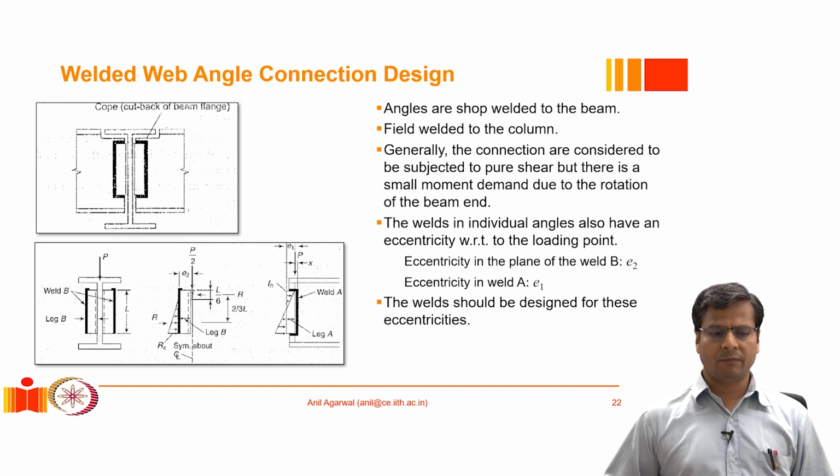But if we need to, then we know the process to follow, and to be on the conservative side, some designers prefer to do that. In fact, the textbook by Dr. Subramanian also recommends the same method to be utilized. Here you might also notice that in such situations we should always provide a return weld at the top. We discussed this when we were talking about the dimensional restrictions on, and the termination of, a weld. The return weld is essential near the top of this kind of weld.